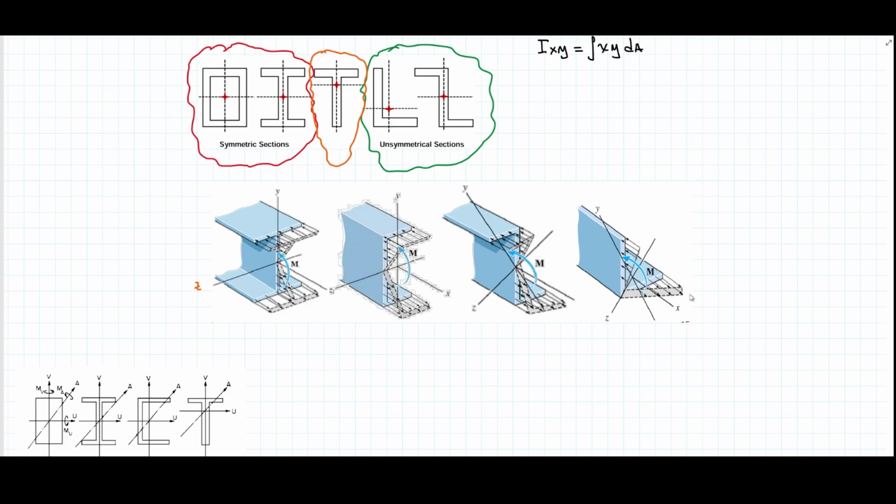And also, if the section is so irregular, I not only need to find the orientation of the principal axes, but I need to find also how the neutral axis is located, because if I want to move the analysis forward from the stress part to the deformation part, I know that in a bending situation, bending occurs around or about the neutral axis.